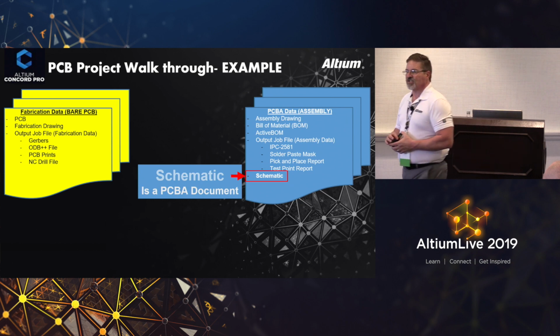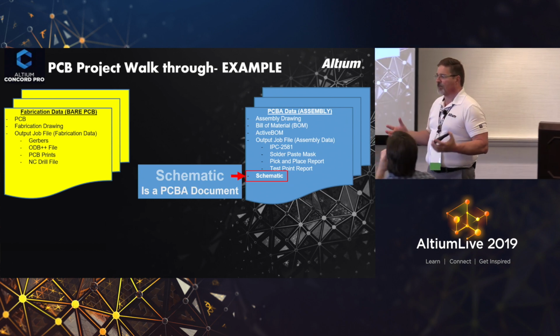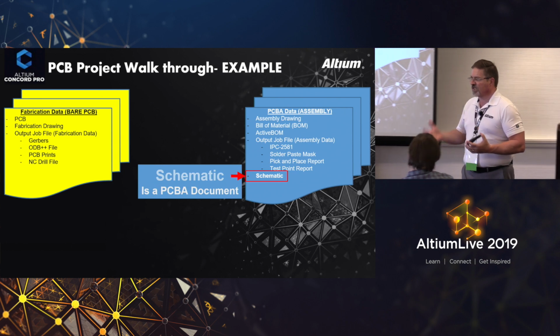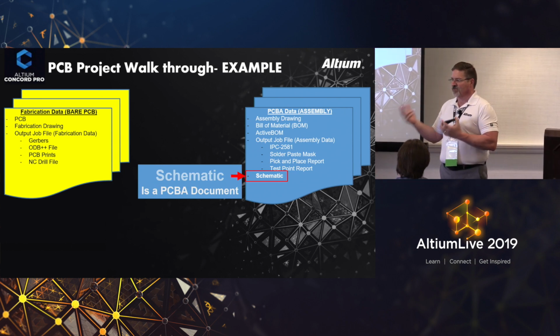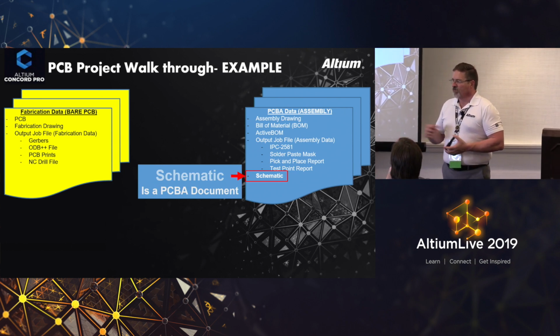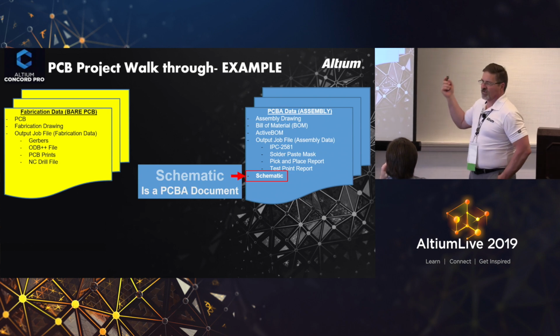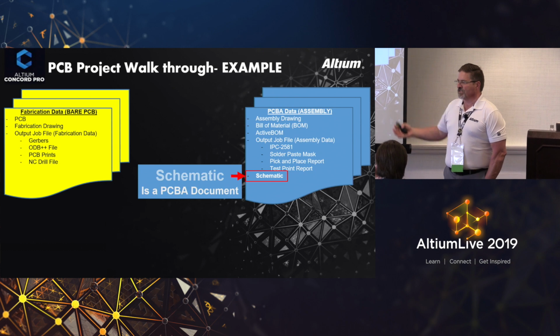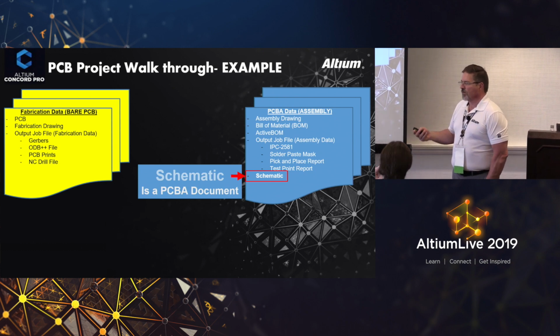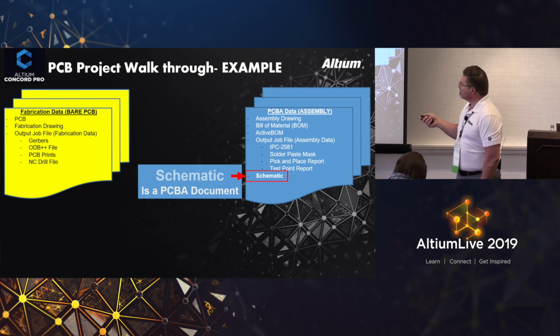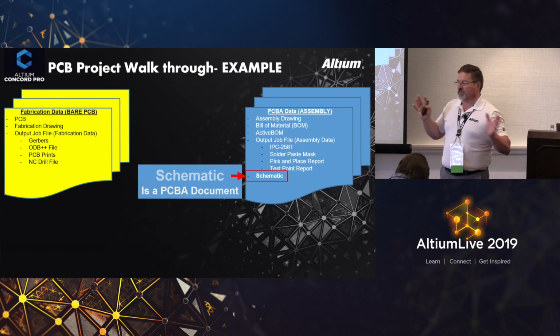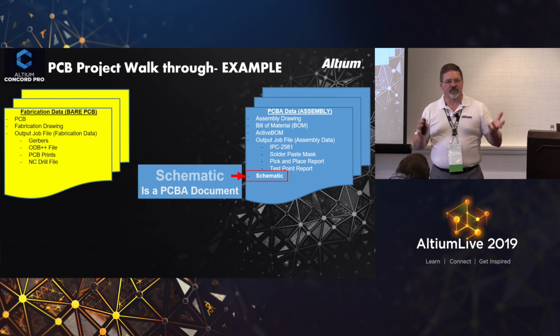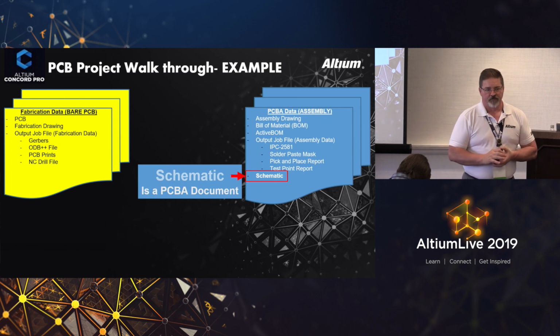Then we have to actually change something. We have to change copper. We have to make a change that would impact the Gerbers. Then we bump everything up to the next revision level. That's our revisioning scheme plan that we use, is that whenever this gets bumped, everything gets resynced. All right? That may or may not work for your situation, just keep it in mind.